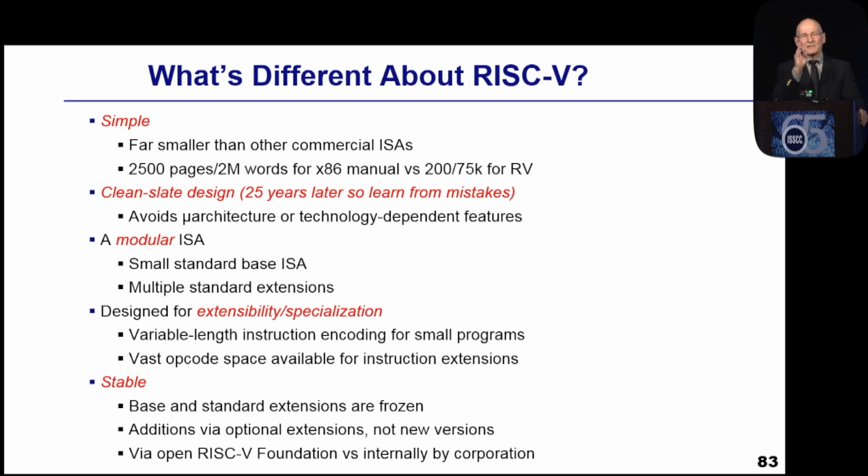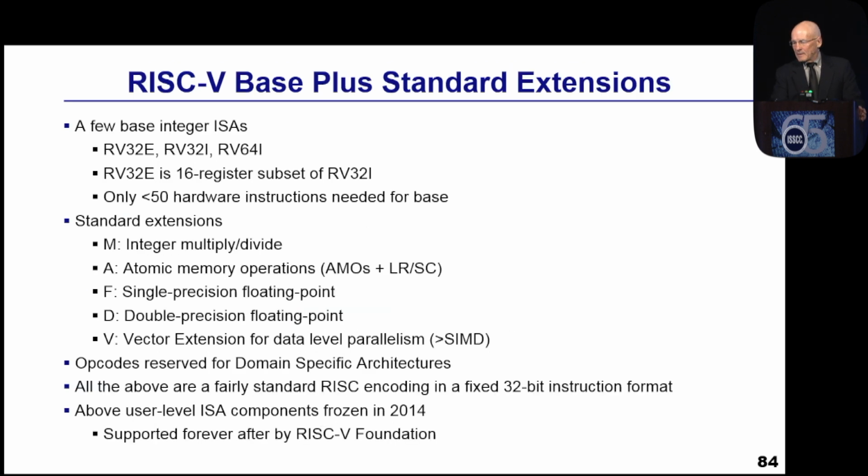It's modular. There's a very small base instruction set that's almost identical to the architecture that was presented here 34 years ago in RISC. And it's designed to support domain-specific architectures through extensibility. There are actually two instruction sets designed, a 32-bit and a 64-bit instruction set. The optional extensions include multiply, divide, atomic operations, single and double precision floating point, and a very nice vector architecture. Opcodes are set aside so you can do domain-specific extensions to it.